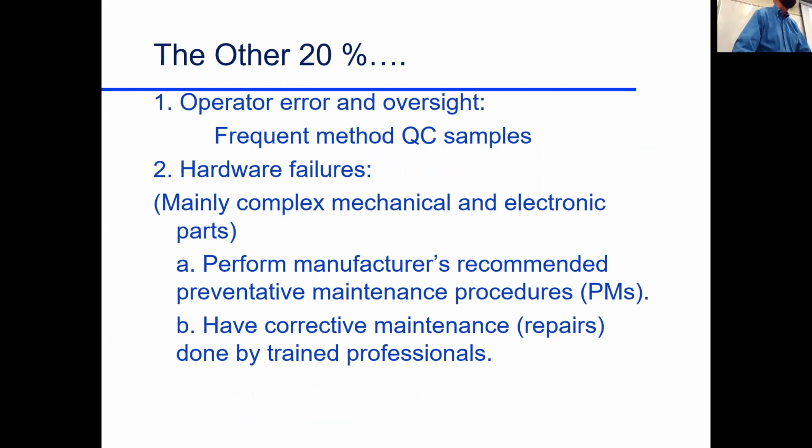Use frequent quality control samples. Again, randomize, put in samples that you know, go through the method with them, go through the instrument with your quality control samples, and interspace them within your analysis. So you know that everything is fine in terms of that. Hardware failures, like I say, are really uncommon.